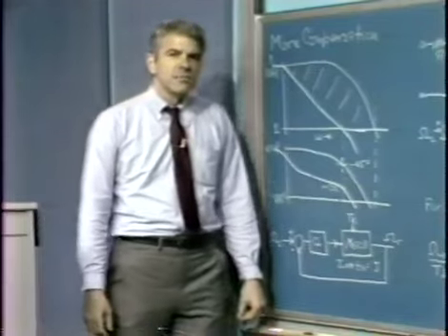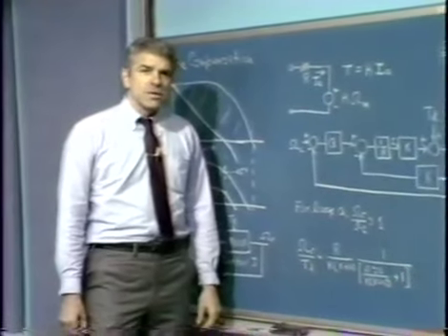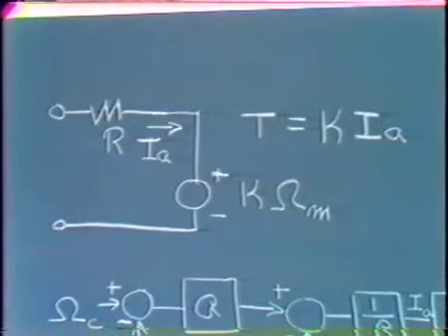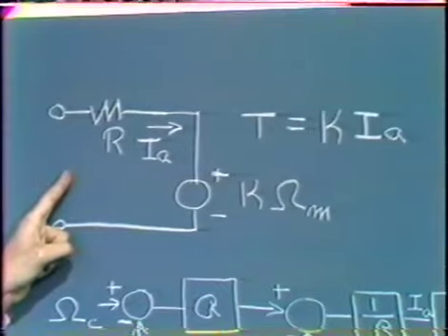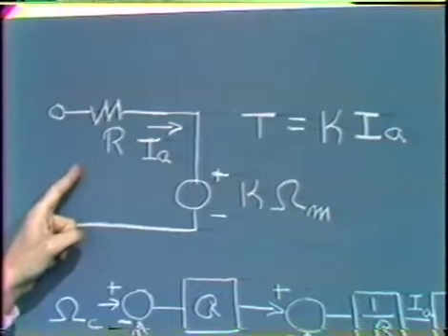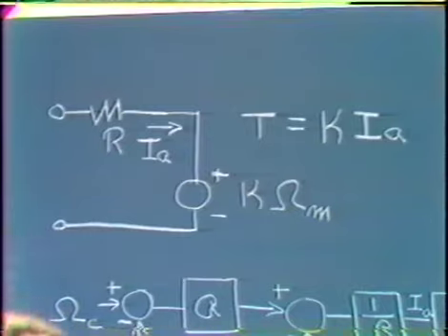We have to start out modeling the motor, and there's a large and important class of motors that are very well modeled by this simple a model. If we have a motor that has a fixed magnetic field, either as a consequence of a winding excited by fixed current, or as a consequence of a permanent magnet, we're very often able to model that kind of a motor in this way.